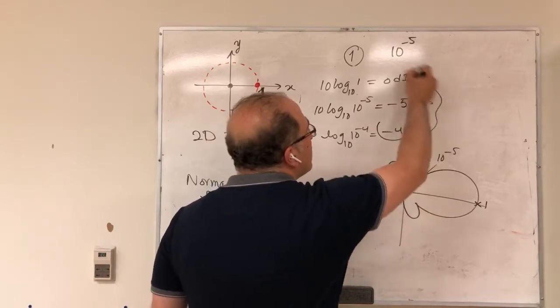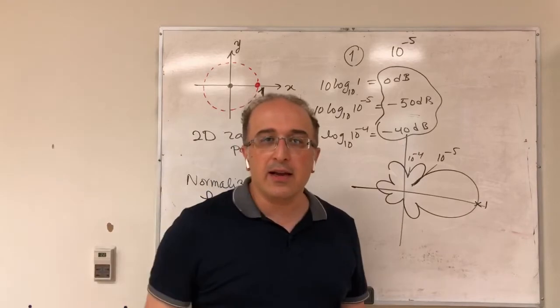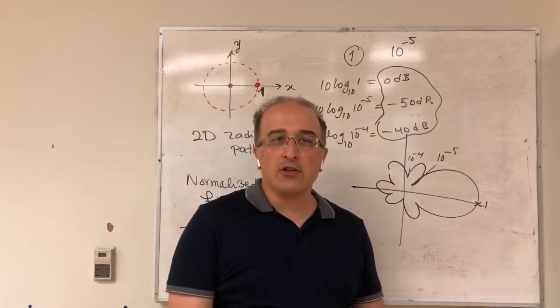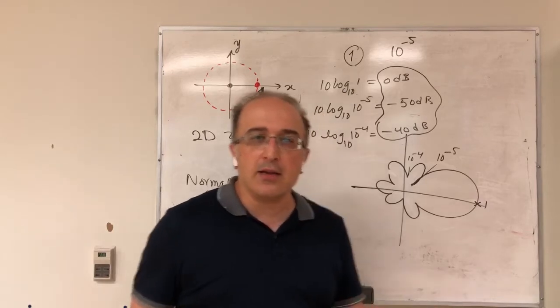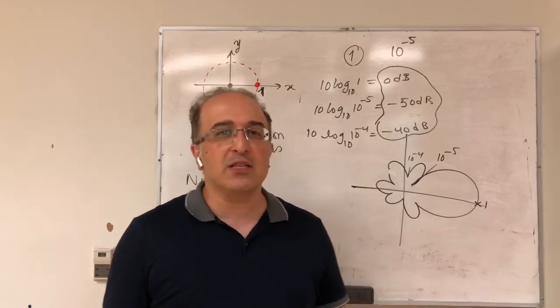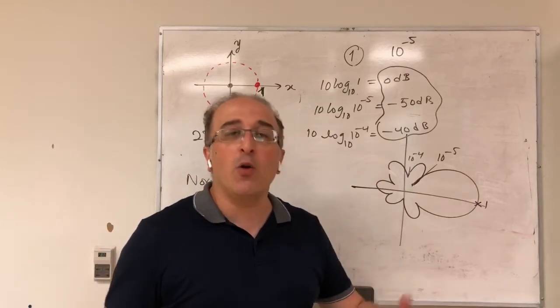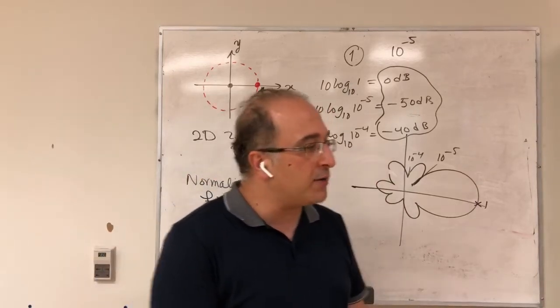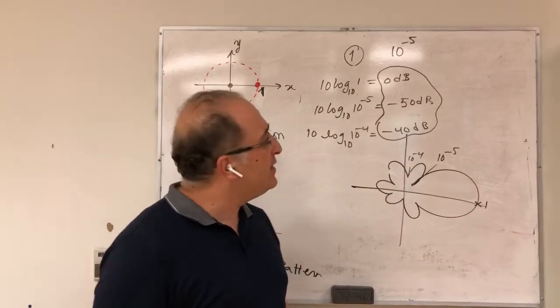Now compare the range here. Now you can actually see them very clearly. You see small numbers better. In antennas, we usually want to see those small numbers because they correspond to our nulls and side lobes, which I'm going to define later on. That's why we show them in dB.